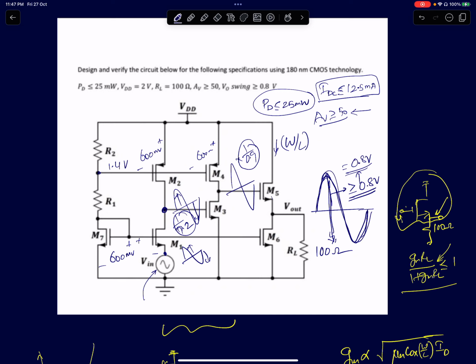And in an AC analysis, you can get the DC gain value and verify if it is matching any value greater than 50. So 100 dB, if you have a gain of 100, it is 40 dB. 50 will be lower by 6 dB, so it will be 34 dB. So any value of gain greater than 34 dB, you're fine. You do an AC analysis and find out the gain. It should be greater than 34 dB.